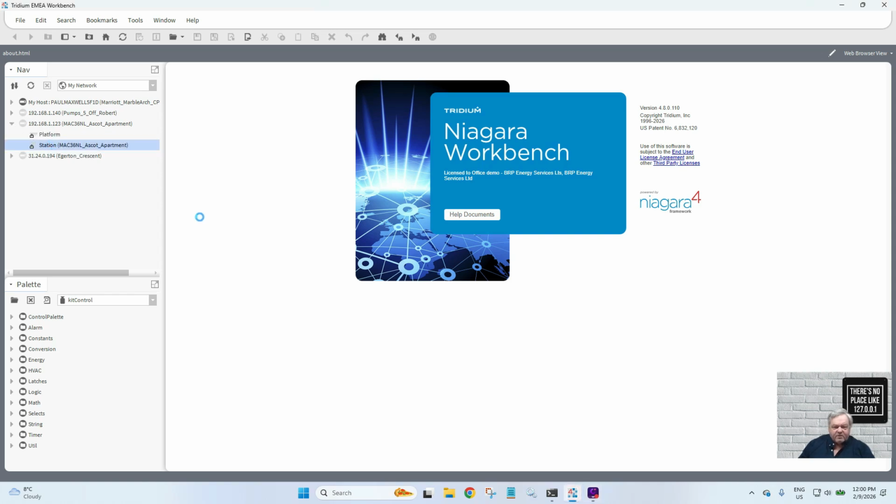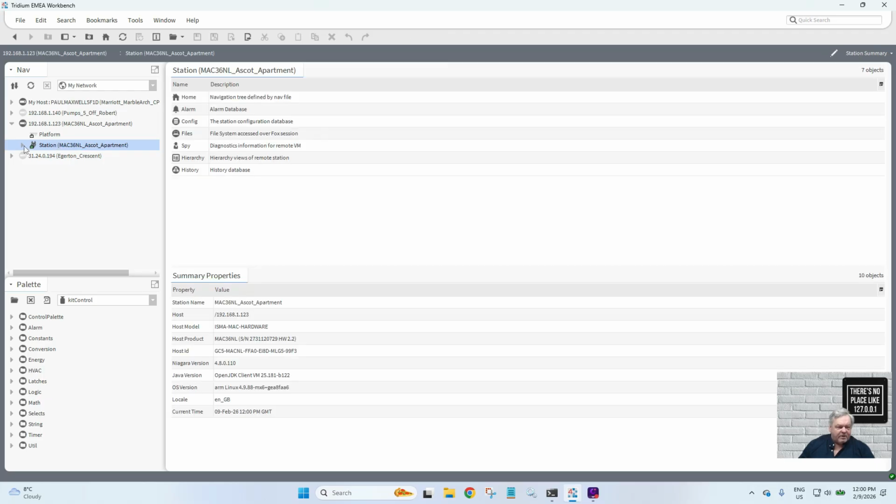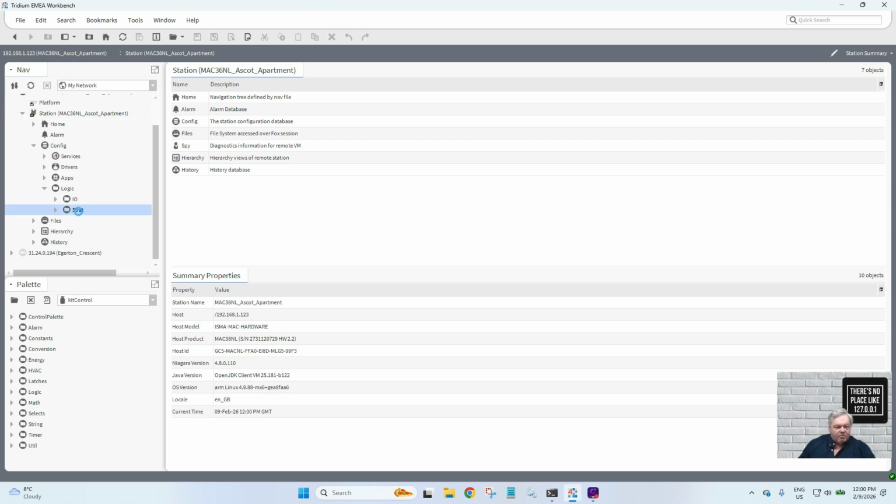So we're going to look at fan coils today. Fan coils are in mostly every building. There are so many fan coils sometimes in buildings, it's unbelievable. The air handling unit would normally feed air from outside into a plenum above the ceiling tiles in the offices, and then the fan coil unit will then feed the room.